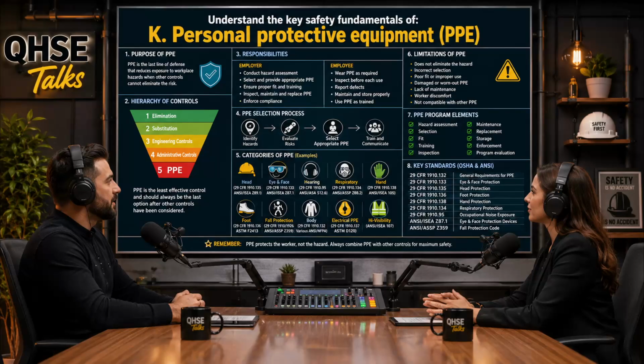So what does the hazard assessment dictate then? It dictates a multi-layered defense. You provide cut-resistant Kevlar gloves and sleeves, that's your PPE. Okay. But to align with the PTD philosophy, you integrate that gear with administrative controls. You design workstations that minimize the need to blindly reach around the sharp materials. Oh, so changing the workflow. Yes. You implement strict training protocols on material handling. The PPE isn't just a standalone, lazy solution. It becomes a single integrated component of a much broader operational design.